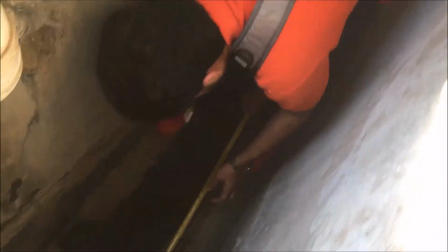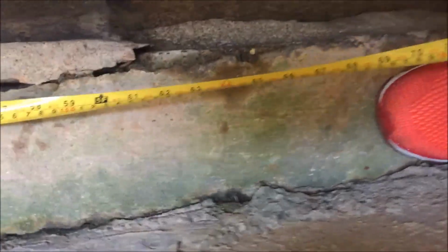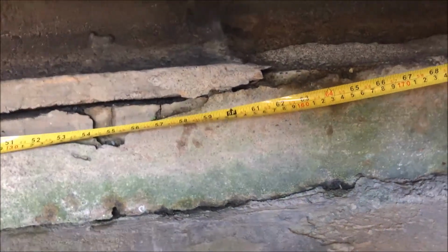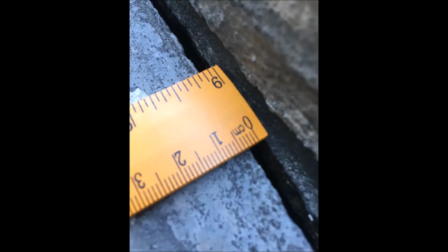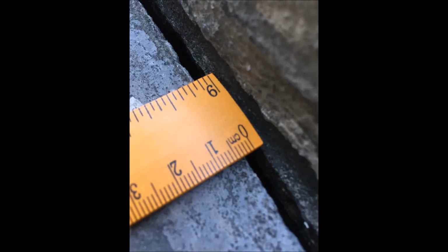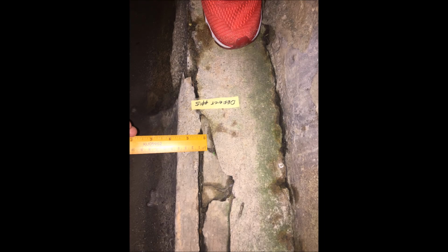The root causes that were taken under consideration were unequal compression of its foundation, shrinkage of clay, undue loads being applied to the building after its initial construction, soil movement during the construction phase, the soil not being strengthened enough, and lastly, the slab is located on the hill, which causes unequal stress. The crack was measured and it was between 50 and 100 millimeters, as you could see in the images.